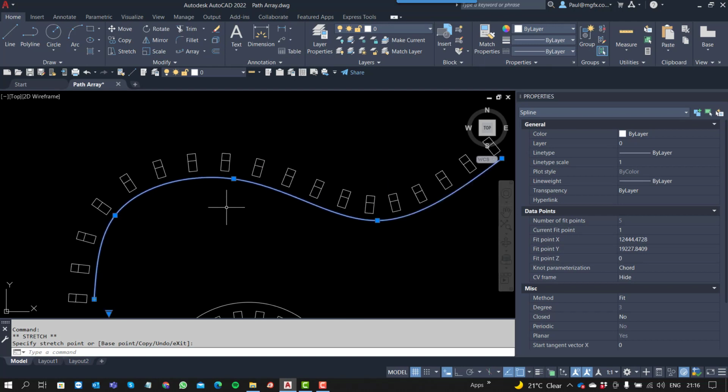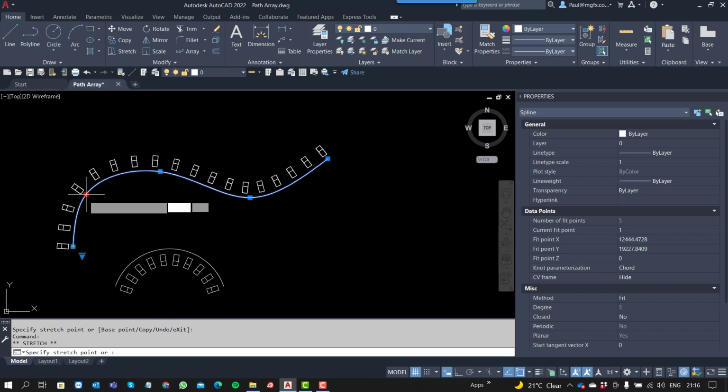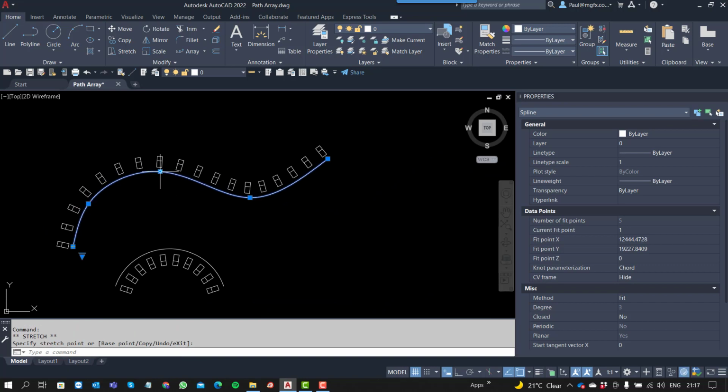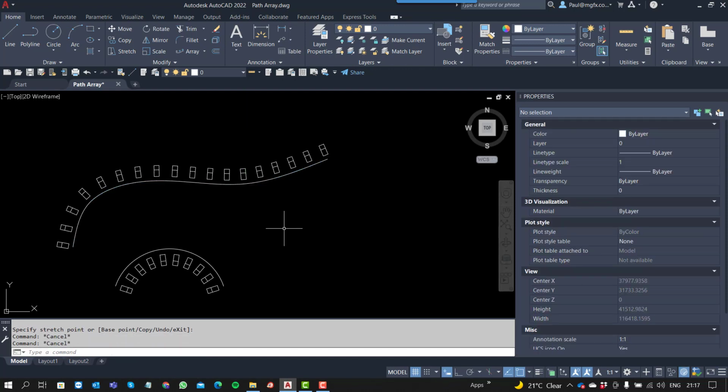So you can imagine, even on a mechanical side, if you had arrayed some rivet holes or bolt holes, if you were doing an aeroplane or some form of equipment where you need drilled holes, how easy it would be just by manipulating the curve. The holes will realign themselves automatically where you would like them with respect to that curve.